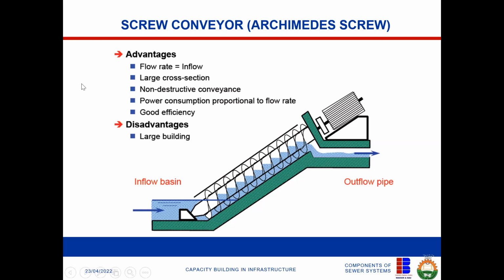So once the water comes from the city, this will be the level of the water. Why? Because it is being sloped, so it can flow. So there's a real tendency that it will have gone down at the point of the treatment plant. So this screw will lift it up again, back to the grid chamber, and then it will undergo all the various treatment steps.